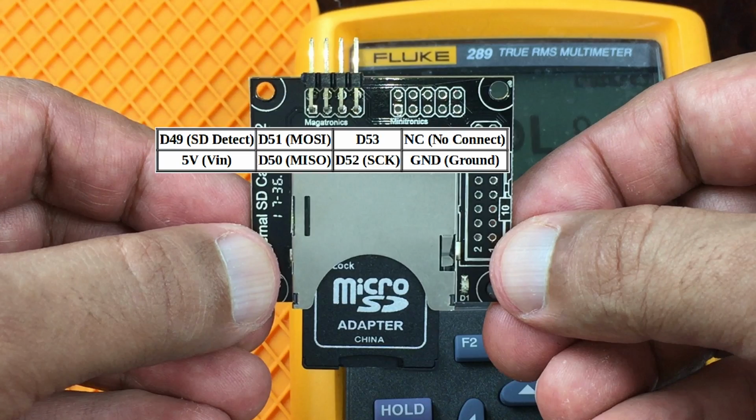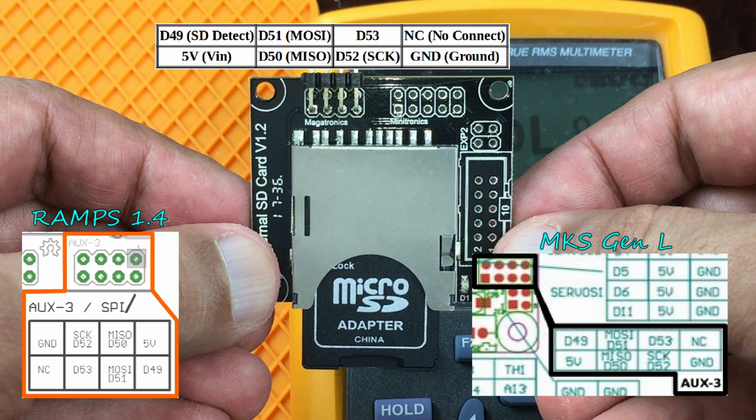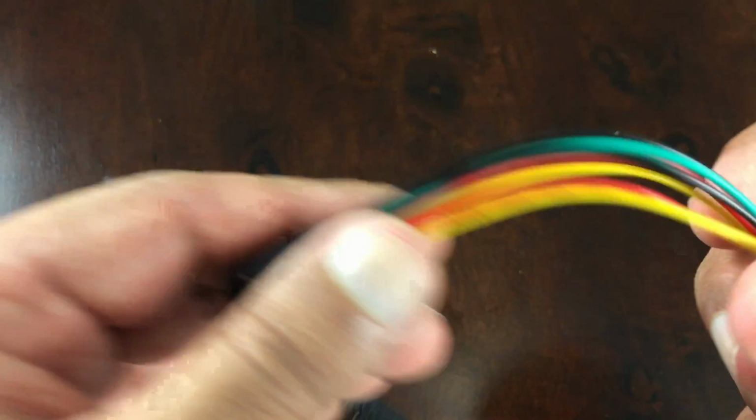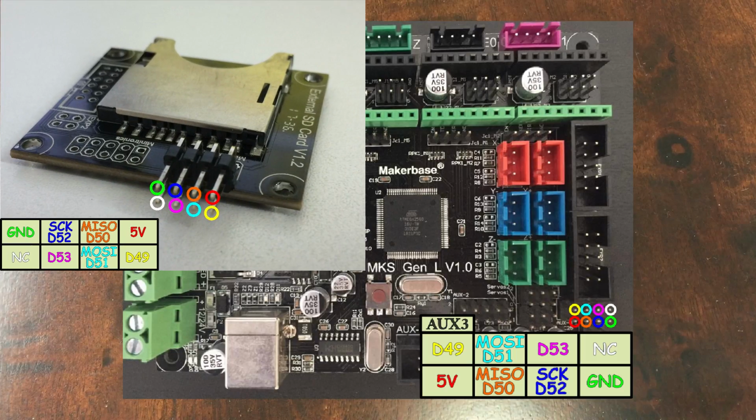From this, we are able to fill in the relative positions of the other pins through comparison as shown. Observe the difference in orientation of the SD-RAMPS connector both on the RAMPS 1.4 and also the MKS Gen L board respectively. The 8-pin Dupont cable which came with the module, however, was not wired properly. The wires had to be rearranged in order to make the connection as shown.